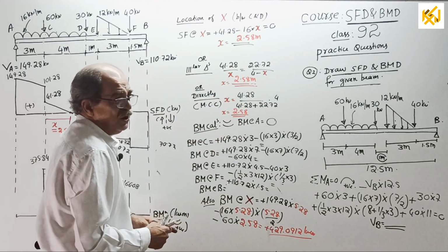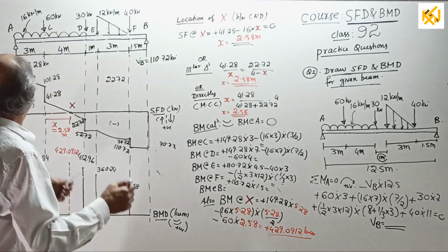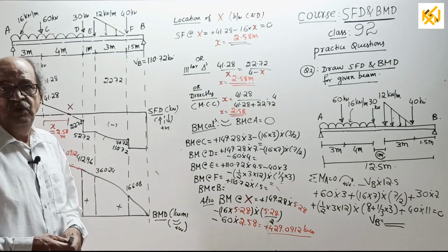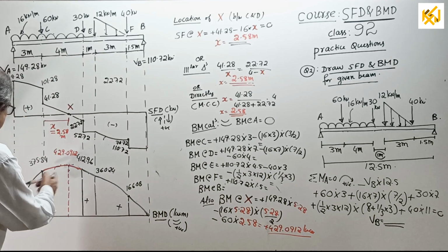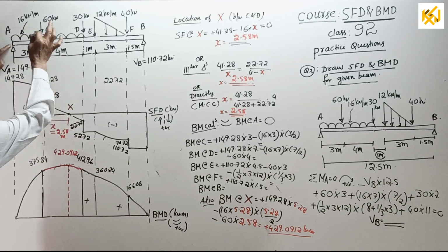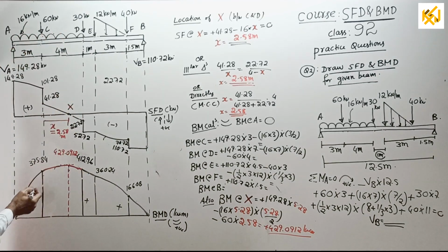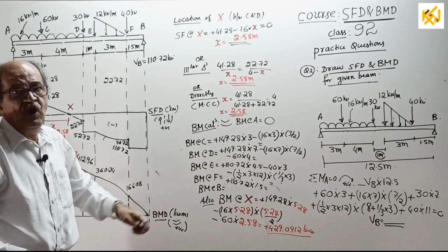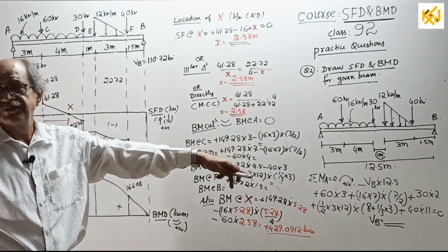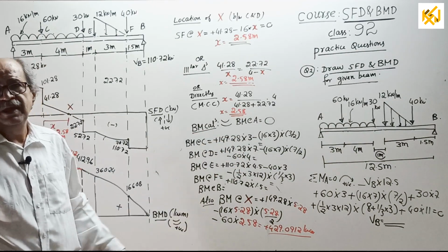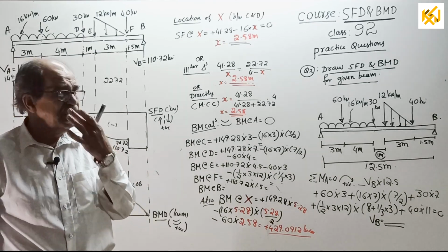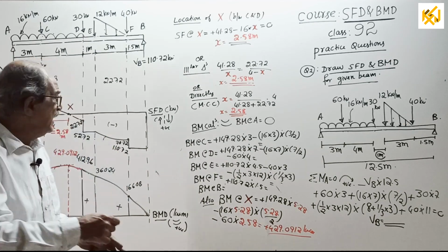Okay. Now go back and draw bending moment diagram. Okay. Now bending moment diagram. I already joined here. See, A to C second degree parabola. If I want to write here now, just to understand, parabola of second degree, actually not here. You have to write all those somewhere there. You know earlier problems. After I finish all the BM calculation, there you write all these things. Here, just mark parabola, that's all.